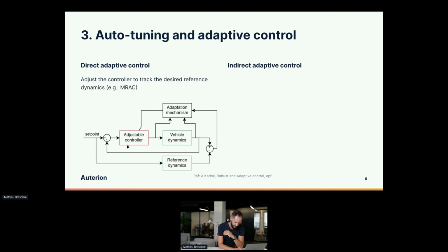How do we initialize the covariance for a recursive least square estimator? Usually you can initialize them to a large value. In our case it's a linear regression problem, so you can initialize them all with some large value, and they will collapse properly. You need to make sure that you have good signal conditioning from the input and the output, roughly the same scale, and in a way you don't need to do anything crazy for the initialization of the covariances.